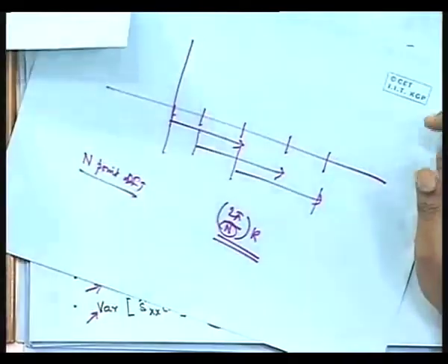So in the first approach you are losing resolution because you are averaging. In frequency you are averaging, so it is quite obvious that you are losing resolution. In the second approach you are not averaging in frequency, but since you have divided the data sequence into K segments, in each segment you now have fewer data points. Having fewer data points means in each of these periodograms the frequency resolution is already gone.